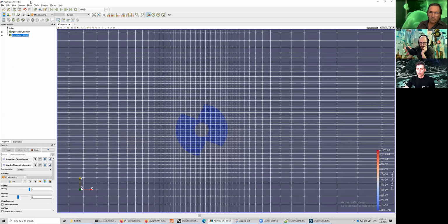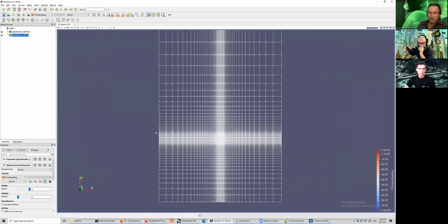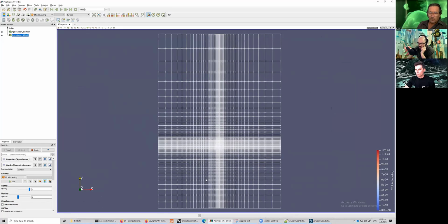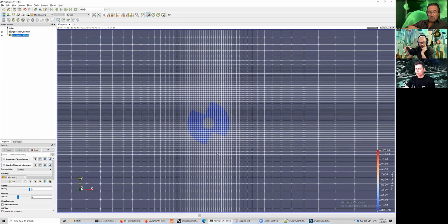And if I load it in ParaView, which is an open source visualization program, very powerful, we need another workshop to detail how it works, and I will share some videos about that. But for now, let's assume that we opened it, right? So we opened the case, and you can see that Butterfly indeed did what we told it to do. It created a gradient mesh. You can see how big the cells are up here. And if I zoom inside, this is our geometry, and you can see the bounding box almost around it with these 4-meter cells, right? And what you can see as well is from the tip of the building, for 50 meters after it, this size is still the same. This is the wake offset we had, if you remember, right?